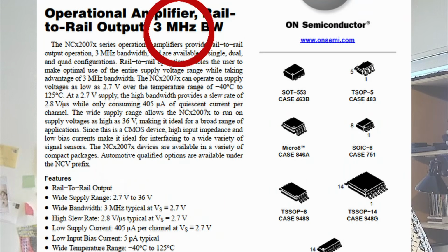Now, this is fundamentally a property of the integrated circuits that you're using. It's also a property of how you design the filters around that IC. For instance, you're almost always going to see some kind of a capacitor on any analog input. And the reason for that is you want to have a nice well-defined capacitance on any analog input. If you have an undefined capacitance, it makes it really hard to figure out what is the bandwidth.